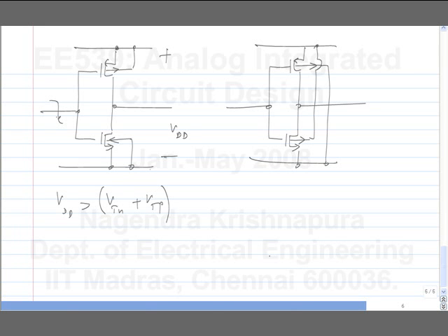So now what happens is that the VBS of the NMOS transistor is positive, equal to VDD, and the VBS of the PMOS transistor is negative and also equals VDD. So you clearly cannot use it for VDD greater than about 0.3 or 0.4 volts, or maybe half a volt at most, but it will lower the threshold voltages. So you can use this with very small VDD. In fact, you can't use it with high VDD. Beyond 0.6 volts, you cannot use it. But it's an interesting circuit.